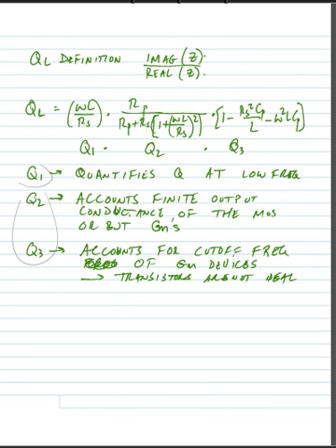Alright, so what we would say is that Q1 is a low frequency quality factor and Q2 and Q3 are due to higher frequency components of the signal. If we multiply all these Q's together, we would get some kind of practical quality factor for the circuit, or some kind of practical bandpass behavior for our circuit. We'll solve some examples of gyrator circuits in class on Wednesday.